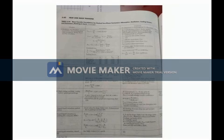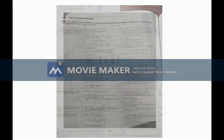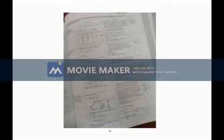Now, for the absorption, we have to use mole ratio coordinates. So, we have to convert the data which is available in mole fraction into mole ratio and then plot. It will be a little bit difficult. For each value of x, you have to find out capital X, that is capital X is equal to small x by 1 minus x. Similarly, capital Y is equal to small y by 1 minus y. So you have to convert all data into capital X and capital Y and draw the equilibrium line.